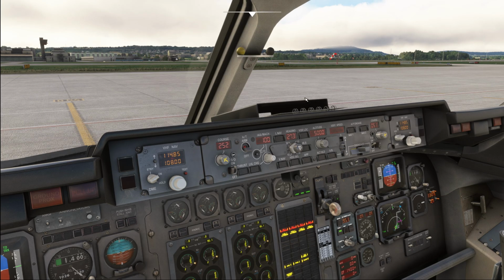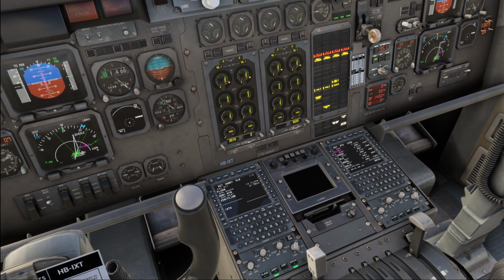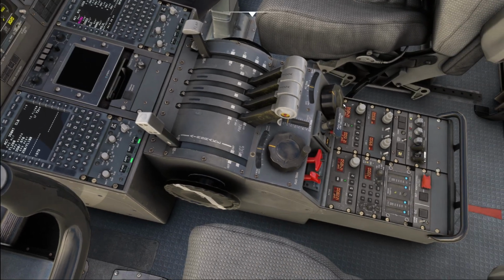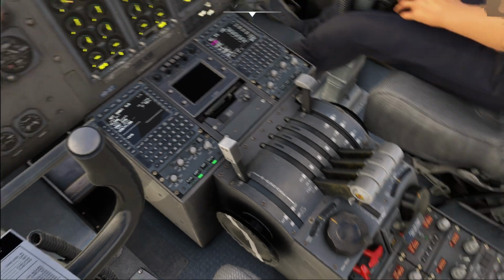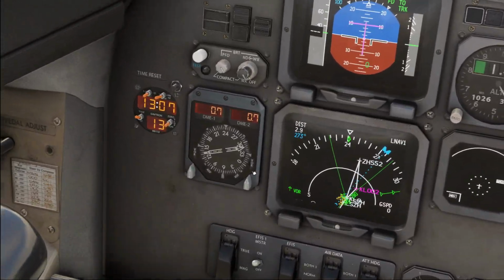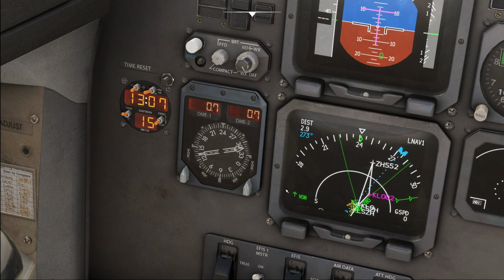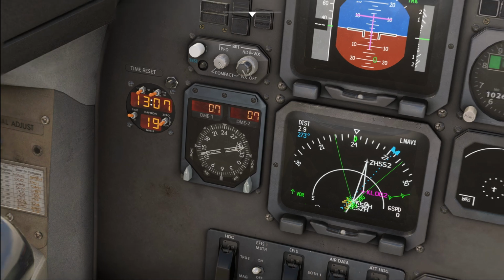Now when this is finished, we need to think about our radio setup. So, do we need anything on the ADFs? Not today, since our SID doesn't use it. Since we don't need the NDBs, we can set the RMI to VOR instead of ADF. So we can use the VOR on both.